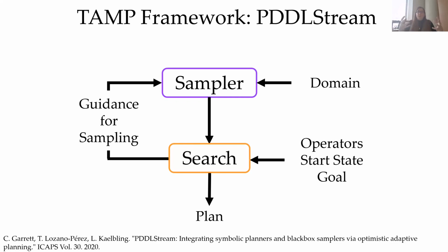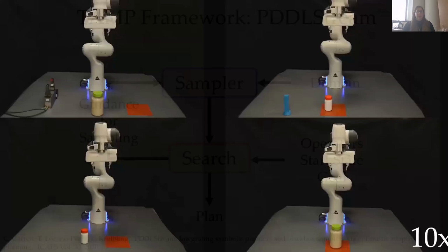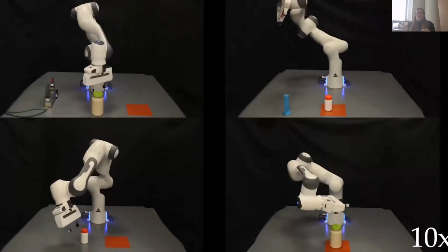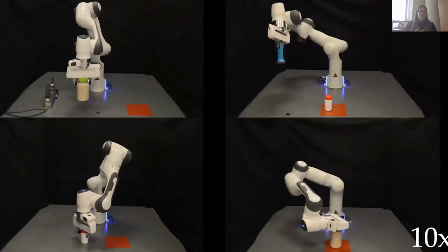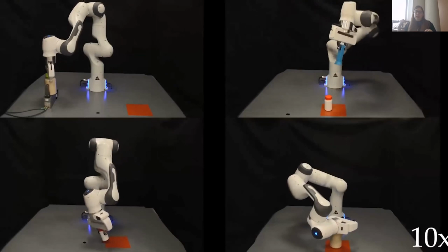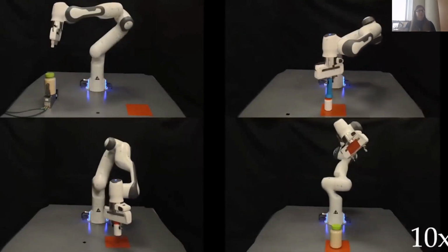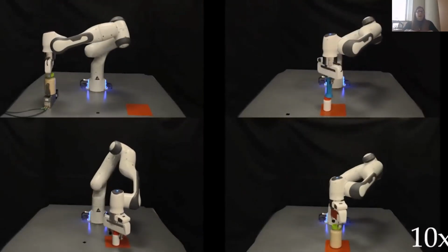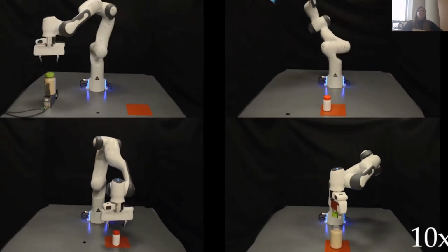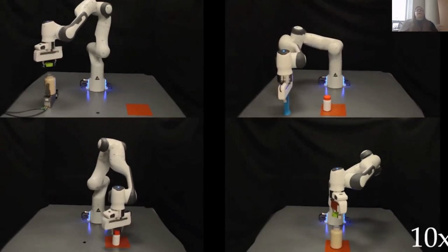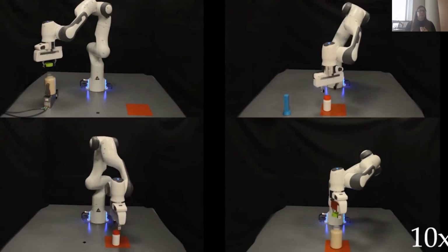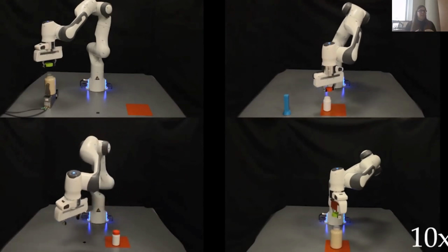So that's the planner that we use in order to search over what are satisfying solutions for this constraint satisfaction problem. And if we bring this all together, now we can actually appreciate what's happening in the video I previewed earlier, where the robot is using a task and motion planner, specifically PDDLStream, in order to find a variety of different solutions given different environments while accounting for all of the force and motion constraints that we've talked through. So in some cases, it's using a vise.